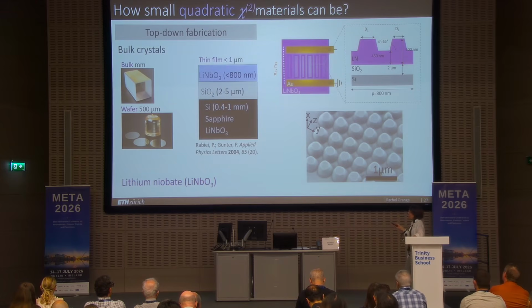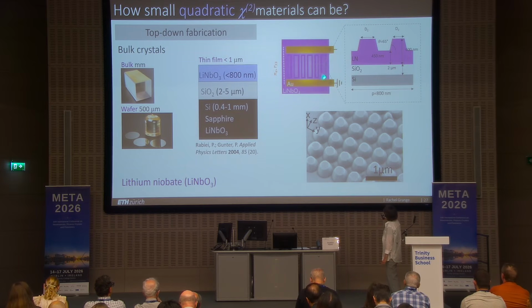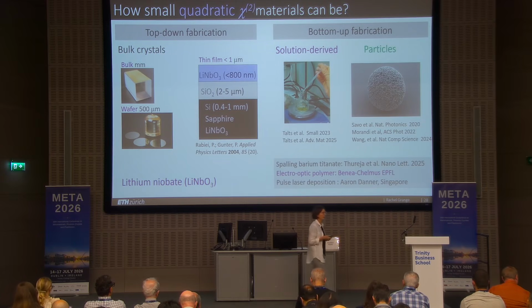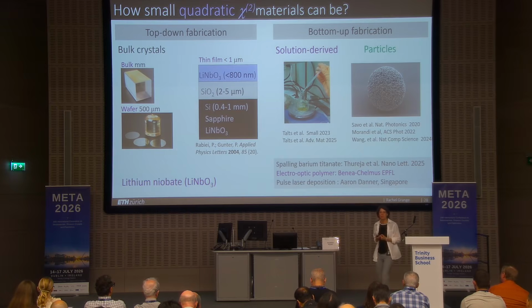Okay, so that's the top-down fabrication I'm talking about, and here you could see, right? This was always a problem for us, that you could not really have straight side walls, and always those pyramids. Even when you look at the side walls of those Bragg gratings, they're also not straight. They're really bent. So the solution for that was to develop our own way of fabricating lithium niobate and not relying on the commercial substrates that are also quite expensive and sometimes difficult to get.